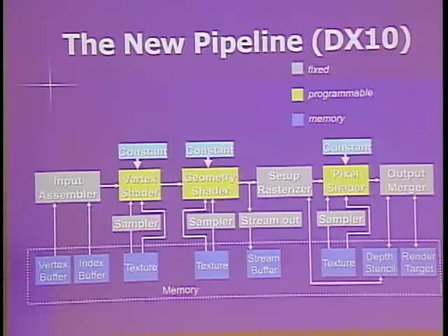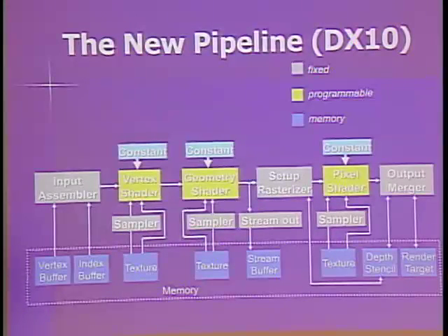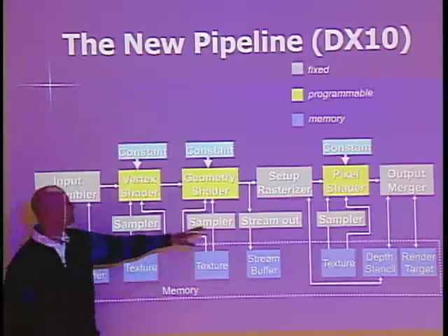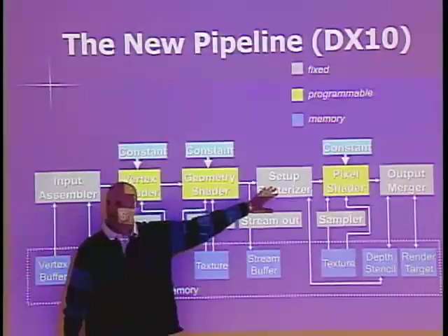So one of the enormous questions in graphics architecture is you've got this big complicated graphics pipeline. What do you build in special purpose hardware, and what do you put in the programmable pipeline? There's not a correct answer to this problem. We are going to have people from NVIDIA and AMD up here, and they will argue, compared to Intel, that they feel more things should be fixed function. They will feel in particular that the rasterizer, for instance, should be a fixed function unit.